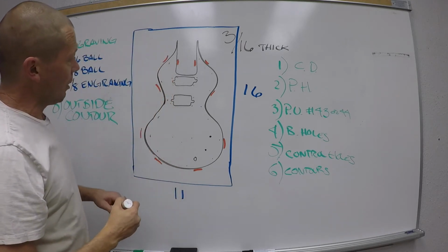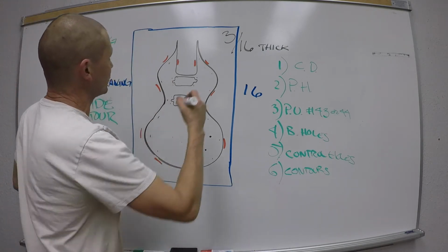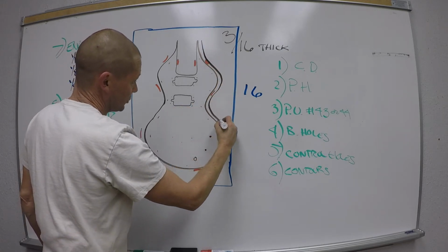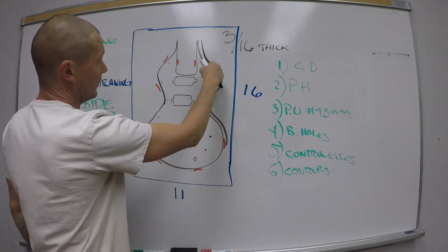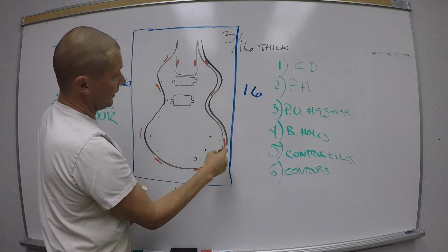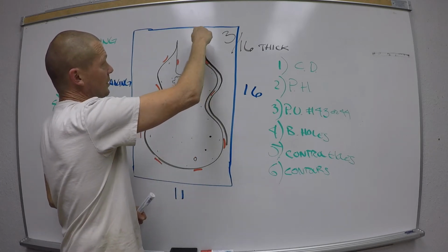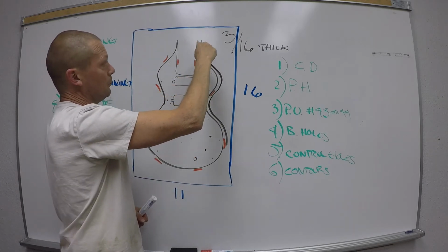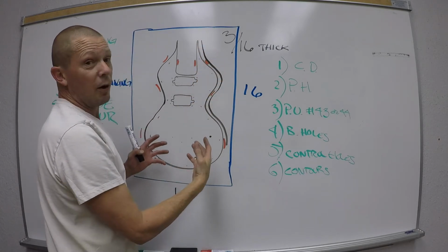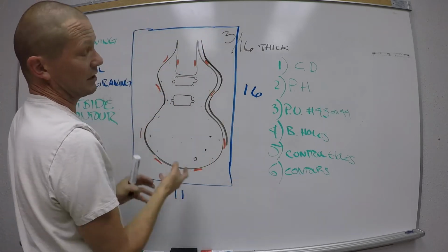And these tabs are, when this 1/4" end mill comes around, now, I'm enlarging this, obviously. This is way bigger than a 1/4". But this is the profile it's going to be cutting away, right? Where the red marks are, it's not going to cut away all the material. It's going to come near, and it's going to lift up, move over, and then come back down. So when I take the part out of the machine, when I'm all done, it's all going to come out with the sides and everything in their tabs.